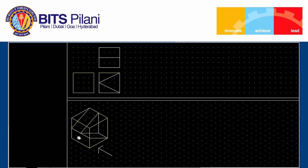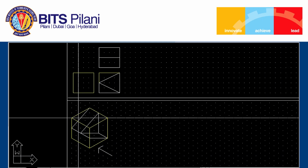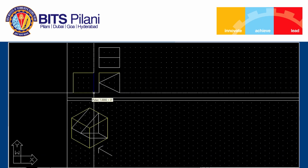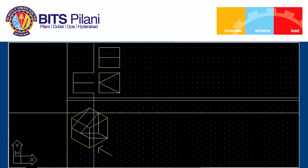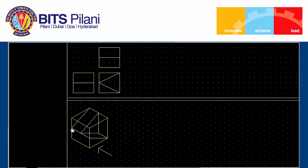I can see this principal surface which is running along the complete depth, height is 2 grids, and then these inclined surfaces which can be seen in the side view. So let us draw the principal surface. This inclined surface, the other inclined surface here, if you see, the depth is 2 grids, height, it will run from 2 grids. So this particular point will appear here.